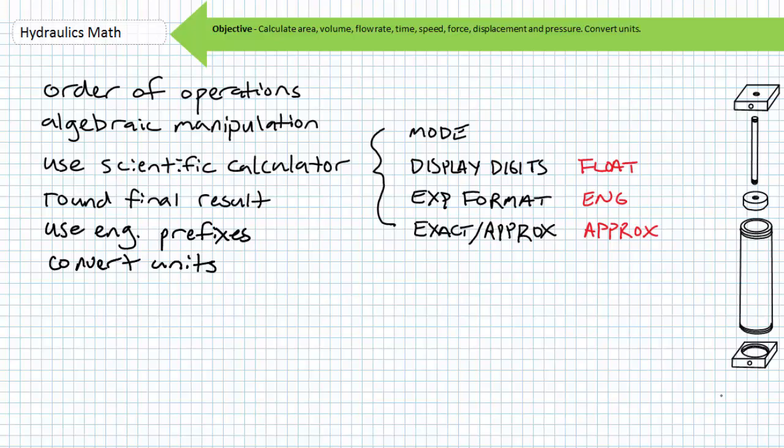Don't blow a hose if your calculations call for an observed pressure of 487.3 psi, and your pressure gauge's needle is pointing to the general vicinity of 480 psi. You're in the right neighborhood. If this needle is pointing at 48 psi or 4,800 psi, you're not only not in the right neighborhood, you're in a bad neighborhood wearing the wrong shade of red and about to get jacked.